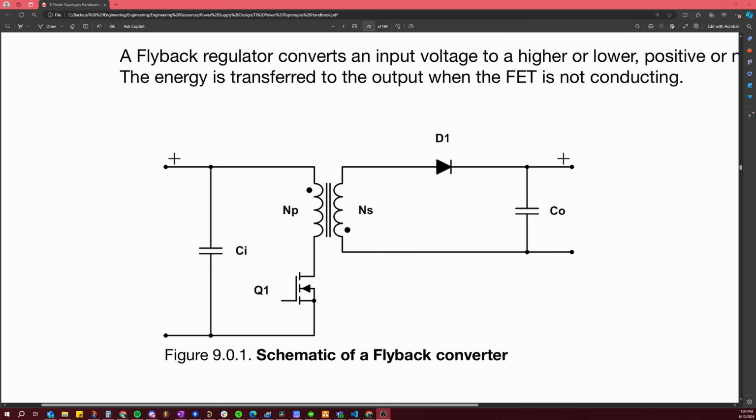Okay, so now we'll talk about the second perspective to understand transformers, and that's going to be looking at it like an electronic component. Electrically, we can look at the transformer like a pair of inductors that are linked or coupled together, meaning that what happens to one of the inductors, you'll have an equivalent reaction in the other inductor.